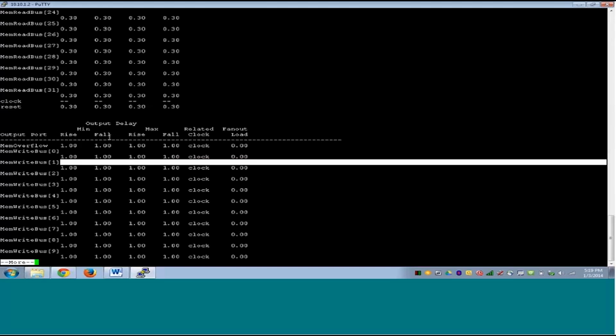For synthesis, the max value is important. We are talking about the worst case, but the min value becomes very important for static timing analysis. So when we talk about synthesis, all the values we give, the input delay, the output delay, we choose the worst case; they are all worst case stuff, since we are worried about the performance. But when we study unit 5, the static timing analysis, the min delays also become important. They also start playing a factor.